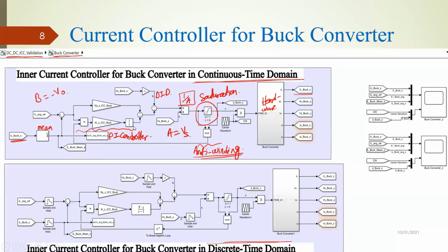I should also have disabled the integrator, but it was not done. And since the speed is 0, the error is positive, and the integrator value kept on rising.